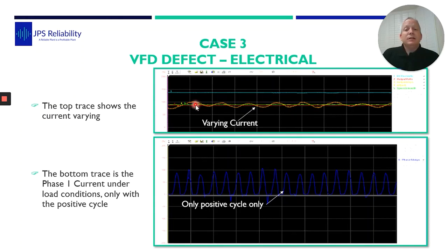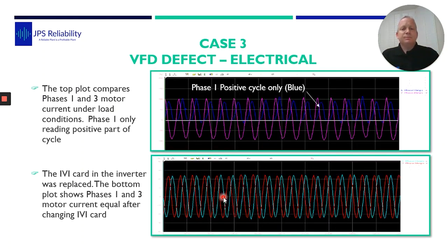So here is a current trace, and this orange plot there is actually a varying current on this motor. And when you look to the 3 single phases here, you could see there's only half a cycle. So on one of the phases to the motor, on the 3 phase, there's only half a cycle. And comparing the 2 sine waves there, you can see a full cycle and the blue line a half a cycle. So we're thinking that is why we were getting warmer on one of the coil packs as such, and why we suddenly saw this 25 hertz.